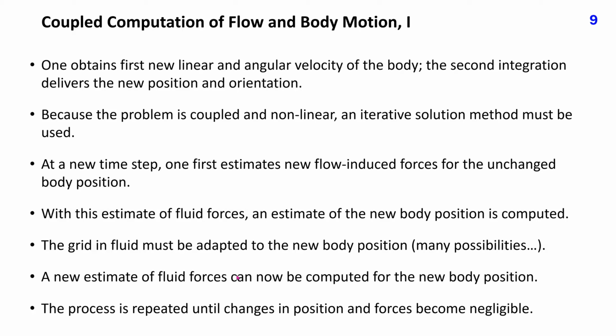The grid in fluid must be adapted to the new body position in every step. There are many possibilities. Some will be described in slides 13 to 18. A new estimate of fluid forces can now be computed for the new body position. The process is repeated until changes in position and forces become negligible.